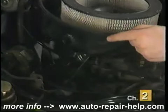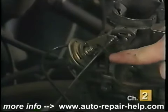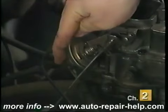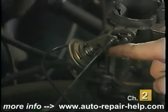They are located underneath the air cleaner on the side of the carburetor and are connected to the choke blade via linkage on one end, and on the other end there will be a vacuum hose attached. Its duty is to slightly open the choke blade on initial engine startup to prevent an over-rich fuel condition.